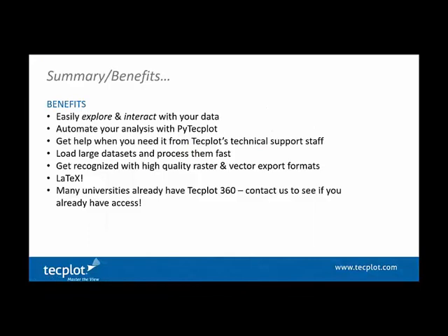So let's summarize what we saw today. We saw a really nice way to load your data and interact with your data without having to write too many scripts. Now we did show the use of some Python, which may be required for doing advanced analysis, for doing really advanced movie creation. But for the most part, Tecplot 360 really allows a way to load your data and interact with it, make all those fine-tune adjustments for your final plots in an interactive manner rather than having to rerun scripts to get text in the right location or a contour legend with the right values on it.